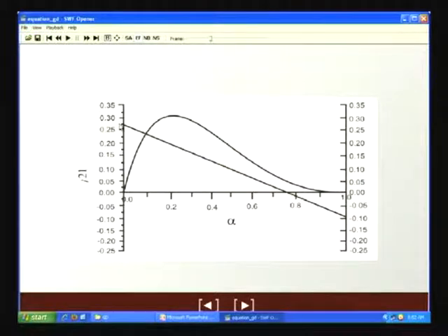And what next do we observe? Suppose we increase J1, that means we increase the liquid flow rate, and keep J2 constant. What happens? The curve will be intersecting at lower and lower points. From a fixed J2, naturally we find that the point of intersection will slightly shift towards lower and lower alpha. Quite expected. Higher liquid velocities, naturally in that case we will have a lower alpha.